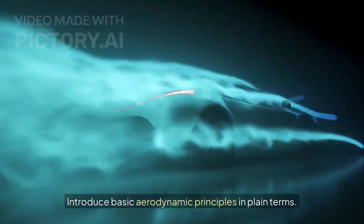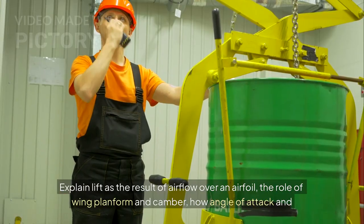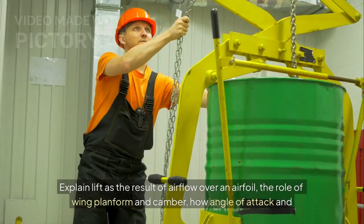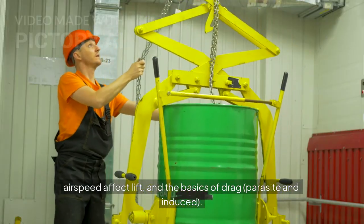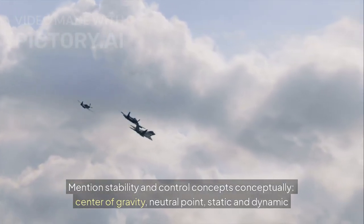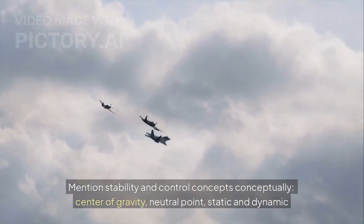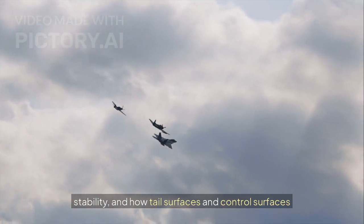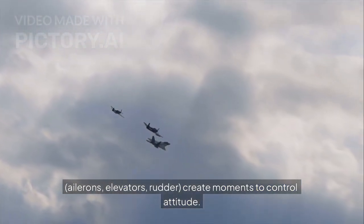Introduce basic aerodynamic principles in plain terms. Explain lift as the result of airflow over an airfoil, the role of wing planform and camber, how angle of attack and airspeed affect lift, and the basics of drag, parasite and induced. Mention stability and control concepts conceptually: center of gravity, neutral point, static and dynamic stability, and how tail surfaces and control surfaces (ailerons, elevators, rudder) create moments to control attitude.